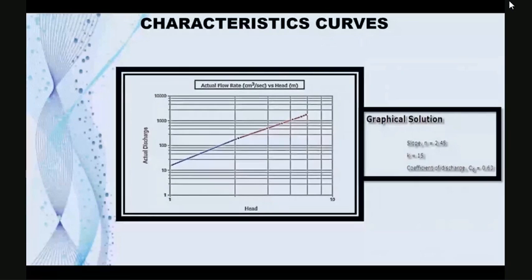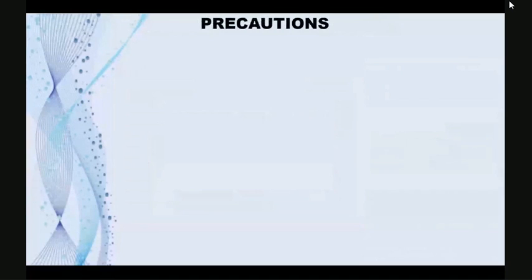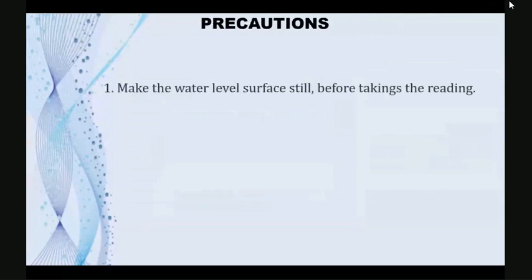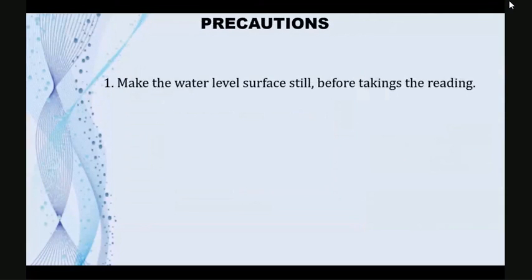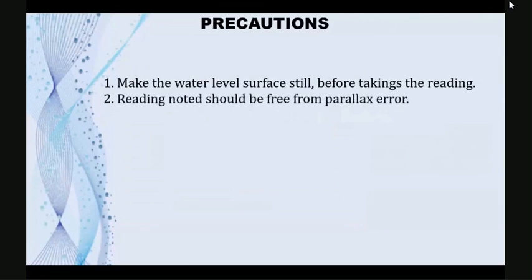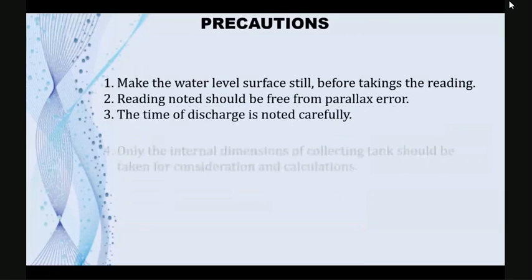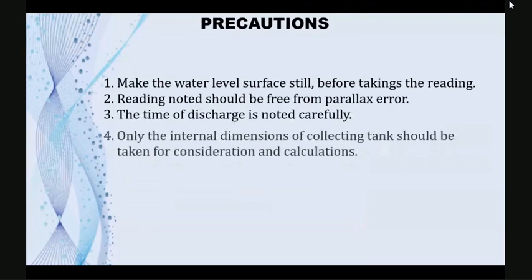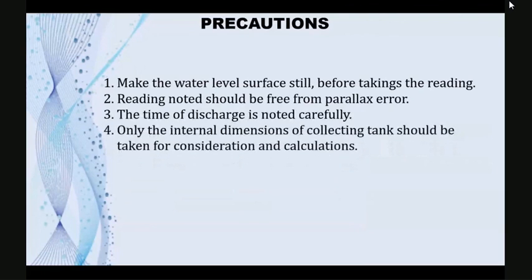Precautions: make the water level surface still before taking the experiment. Readings noted should be free from parallax error. The time of discharge should be noted carefully. Only the internal dimensions of the collecting tank should be taken for consideration and calculation.